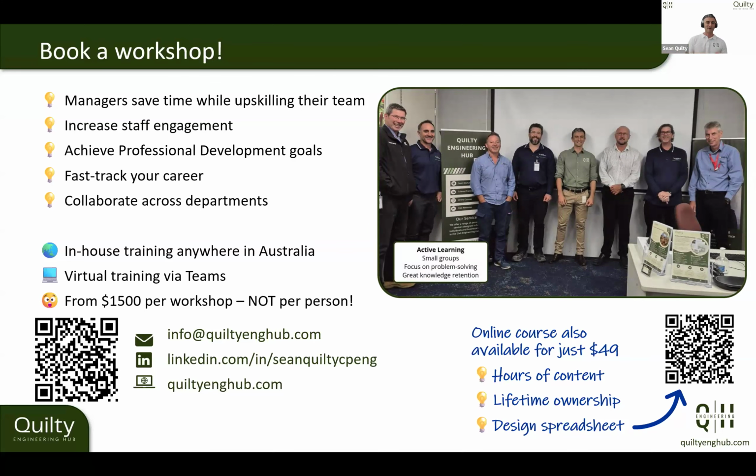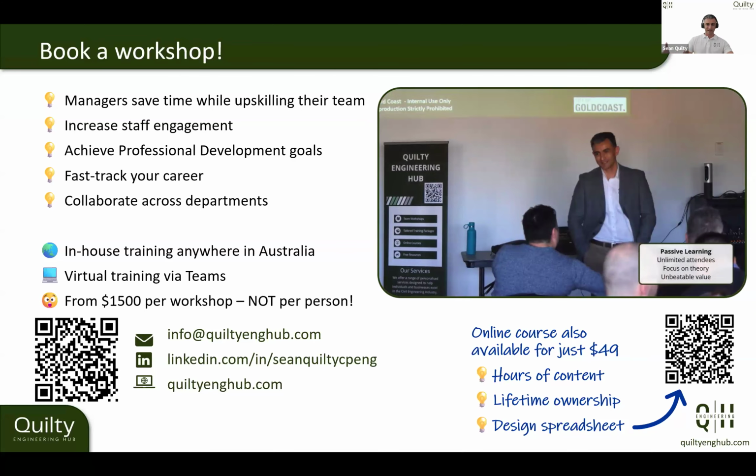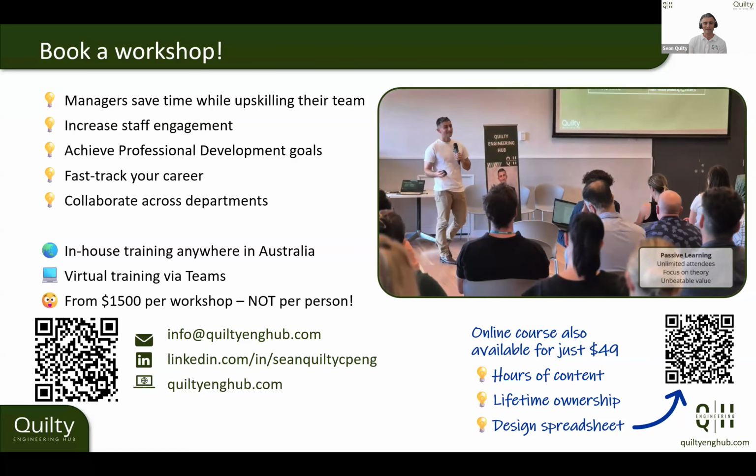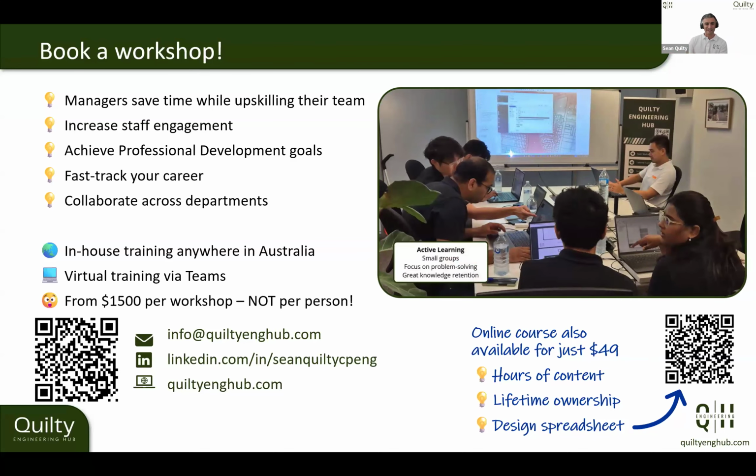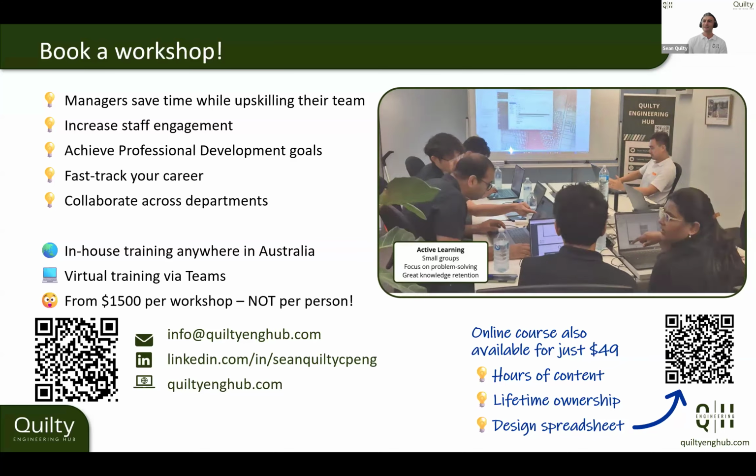Maybe it's a concrete apron with big concrete blocks cast into that apron, so nothing's going to move it basically. Anyway, with those energy dissipators, there are some equations and best practices in there. So HEC-15, I'd definitely have a read through that.